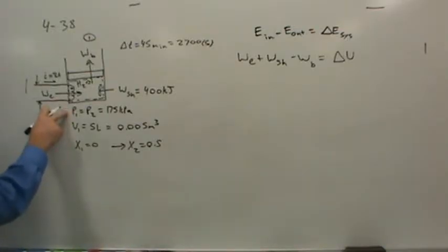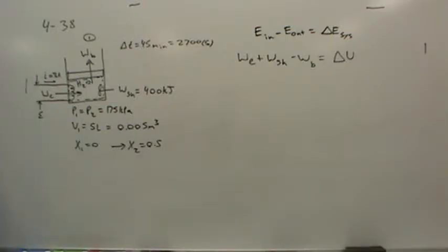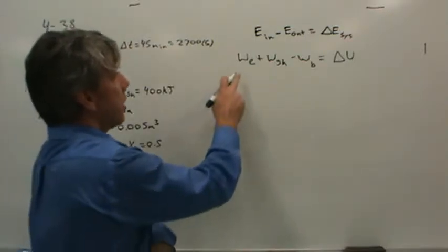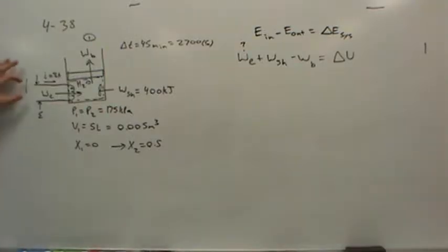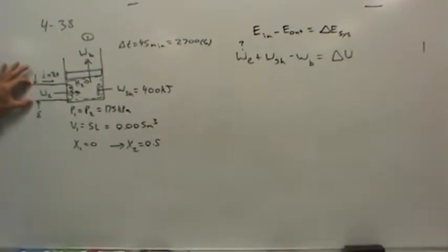We've got the initial conditions of pressure and volume. We've got the quality. We should be able to come up with the amount of mass in the system without too much trouble. But let's continue from our high level, just balancing energy. One of the keys to these problems is almost always balancing energy. Now notice the electrical work is really the unknown quantity, right? Because if we knew the electric potential in volts across this resistor, or this heating coil, well then we would know the amount of energy that flows in. We could figure that out, okay?